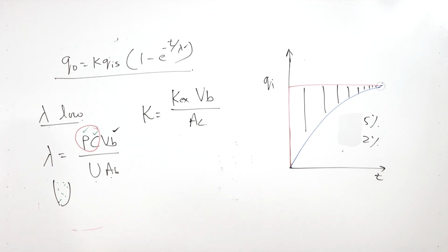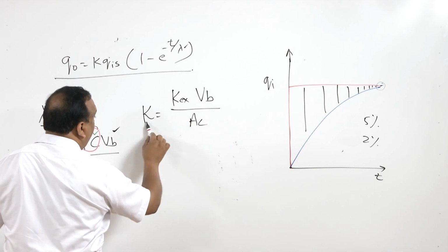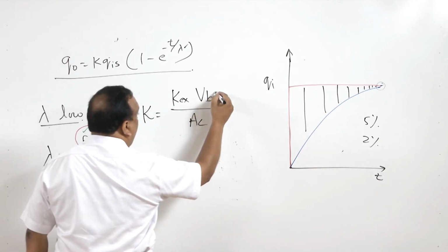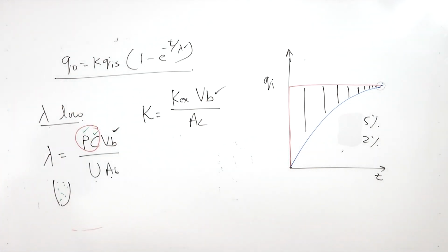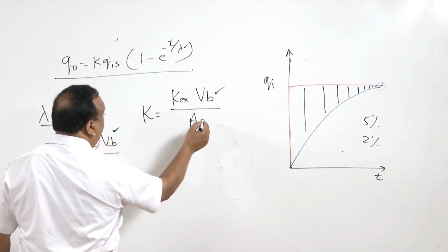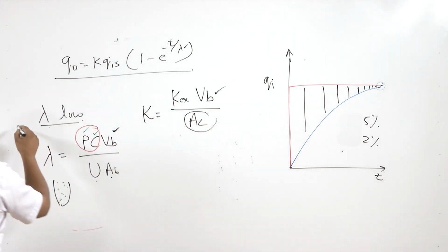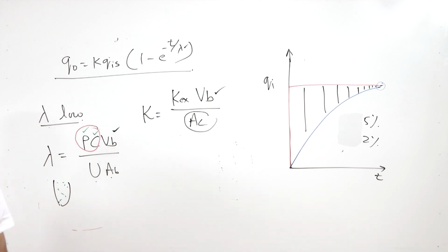I am talking about the liquid in bulb type of thermometer. So, in order to have high sensitivity, we should have a high bulb volume, right? This is the expansion coefficient, and this is the cross section area of the tube where the fluid is rising.